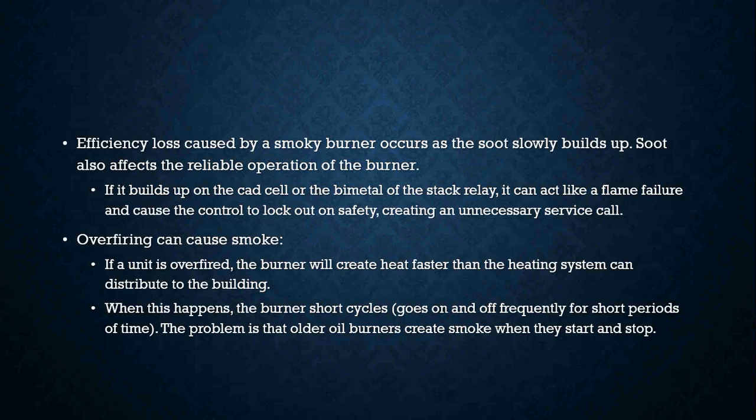Overfiring can cause smoke. Okay? If a unit is overfired, the burner will create heat faster than the heating system can distribute it to the building. You're damaging it. We don't want that.